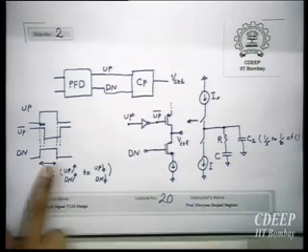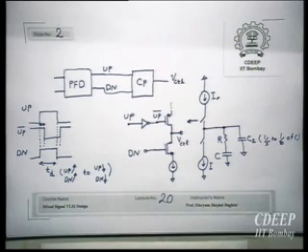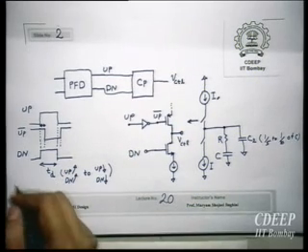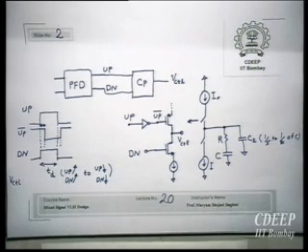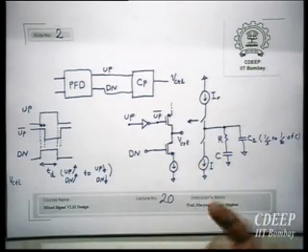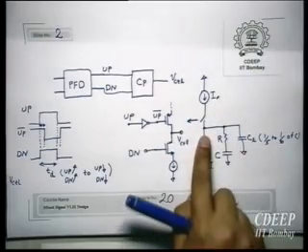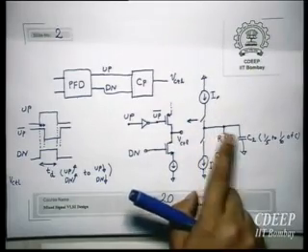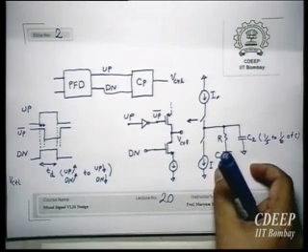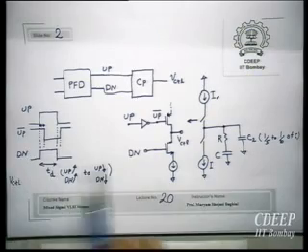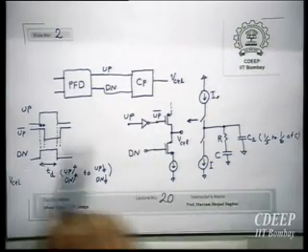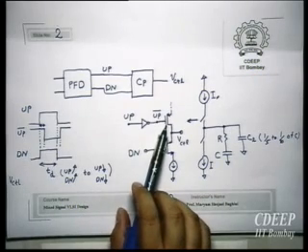So now these are in fact control signals. Therefore, what will happen for the control voltage, VCTL? Ideally we would expect both of them to be on simultaneously, meaning that we should not expect any current to be given to this RC network. But practically, if you look, up bar is high, therefore this switch is off.